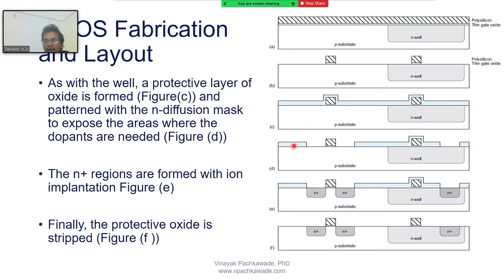The remaining area got protected by the SiO2 because the photoresist was present on top of that. And then I again took off the photoresist from the top of the SiO2 also. So this is how, because here is the active area of N plus, active area of N plus, and active area of N plus, I repeated the same procedure.